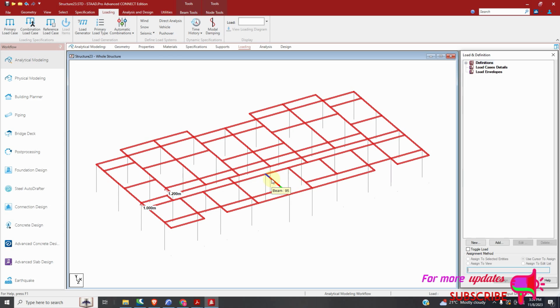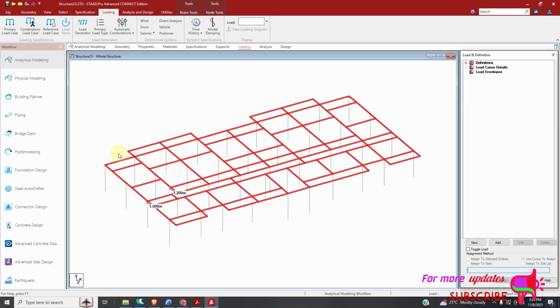So there is a master slave node which will control the way all the other nodes are moving. If it's moved, then the others will move. So if you want to model using the floor load, you can do that, but you have to add a master slave node. So I can just, because let's say there are three floors, I can just do that for both of them. I don't think there's an issue.